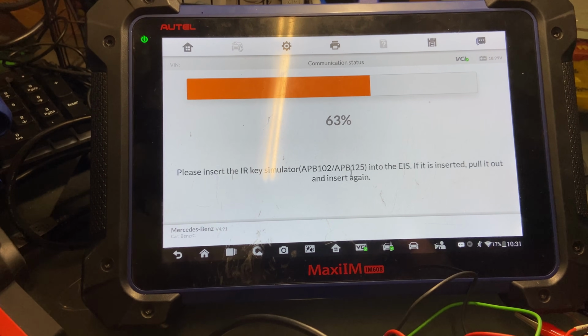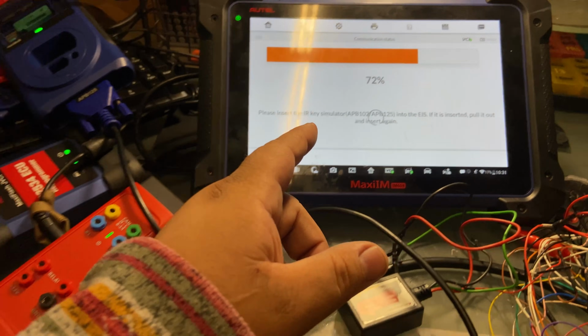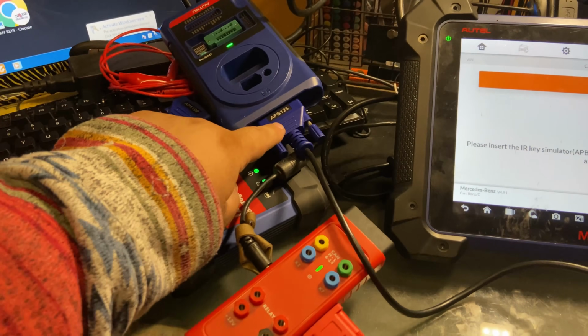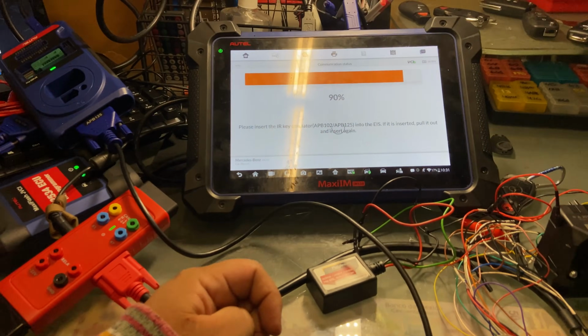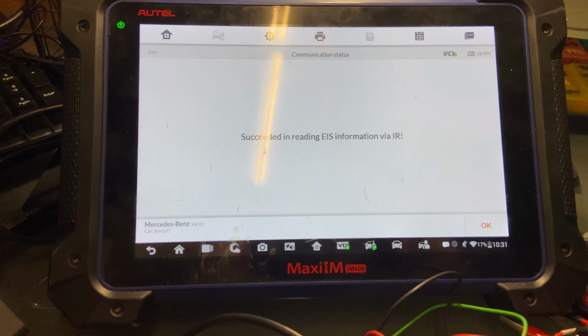Take your key out of the ignition. Does it start? Sometimes people think that the key lost its programming or broke, but it's just a steering lock, and you have to be able to tell when it's that issue.